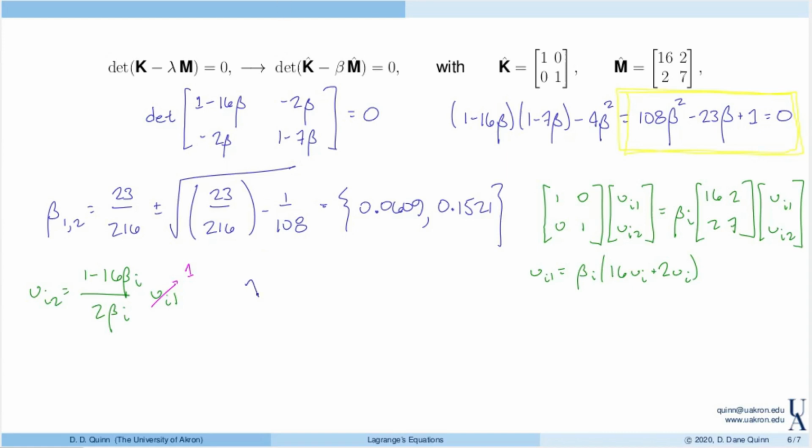we see that lambda, these are the eigenvalues, is beta times k star over m star, as on the previous slide. For this problem that ends up being 27 beta times k divided by m. So we have two solutions. Lambda 1 is 1.644 times k over m. Omega 1 is the square root of lambda 1, which ends up being 1.282 square root of k over m.